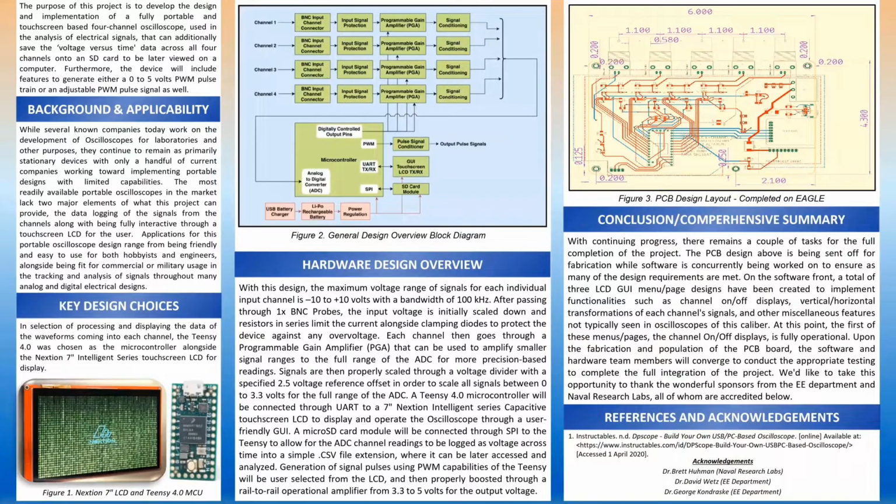Generation of signal pulses using PWM capabilities of the Teensy will be user selected from the LCD and then properly boosted through a rail-to-rail operational amplifier from 3.3 to 5 volts for the output voltage. And next, I'll give it up to Aziz for the PCB design.